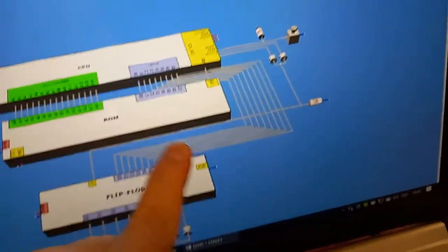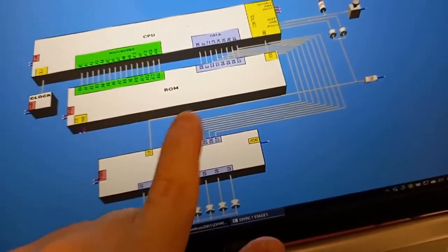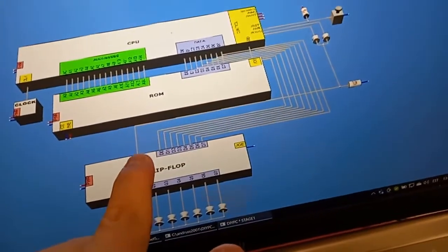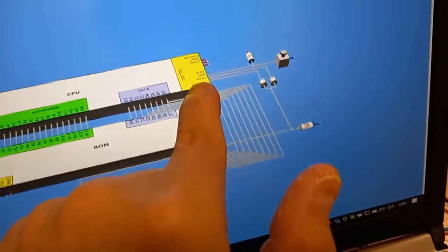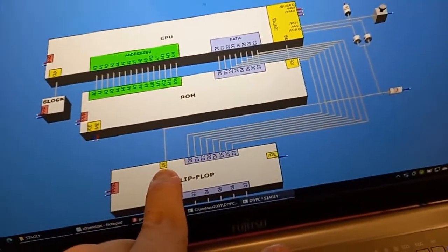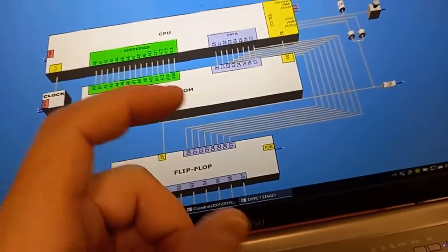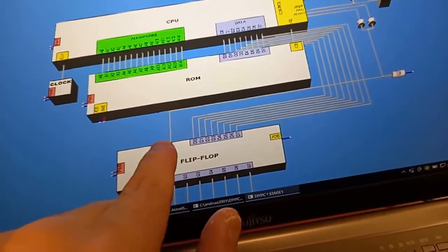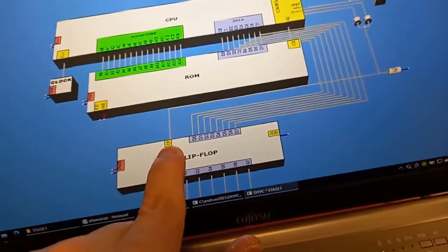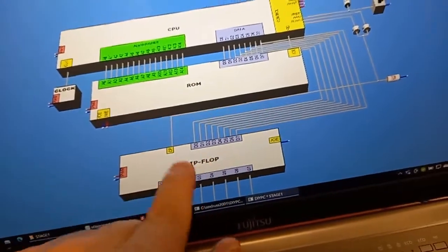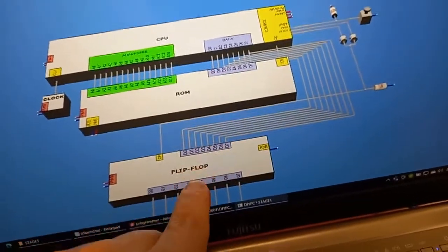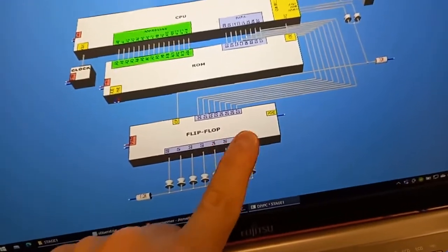And also, since it's connected to the flip-flop, when the CPU is sending something out, it's drawing to 0 these 2 pins. They go here and are connected here, and for the flip-flop that means like pressing the capture button of a camera. Usually this pin is high, and when the CPU is outputting something, it makes it low, and that's the moment that the flip-flop reacts. It copies, it duplicates the input, in our case byte CC, and puts it to the output, puts it here.